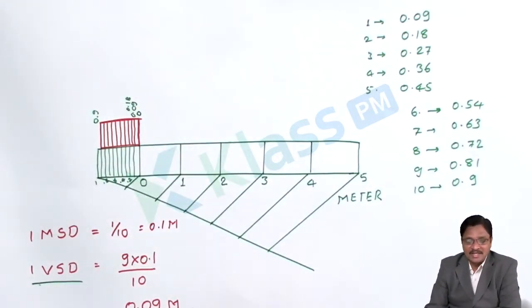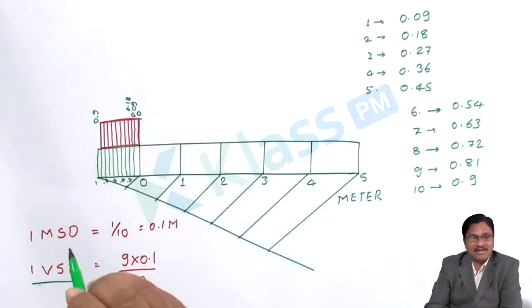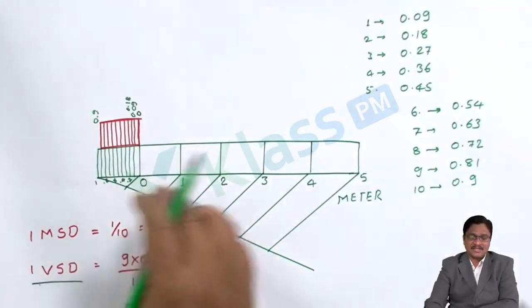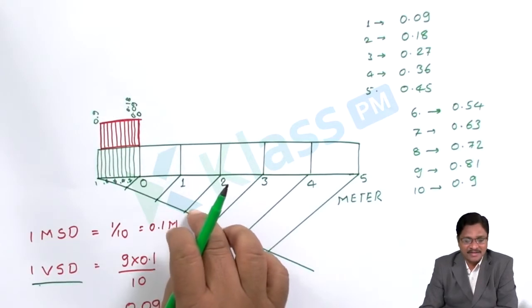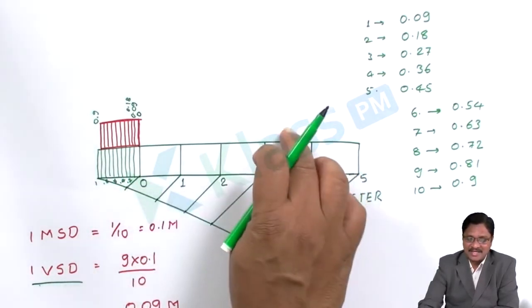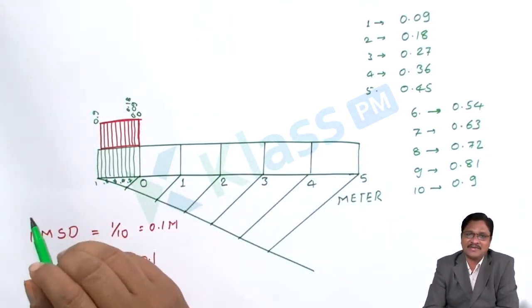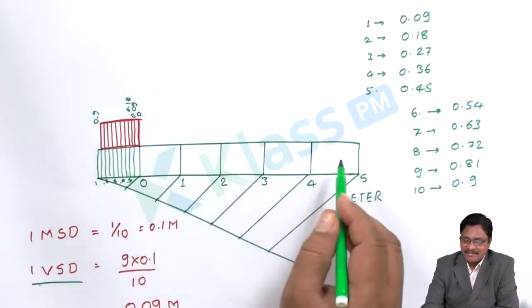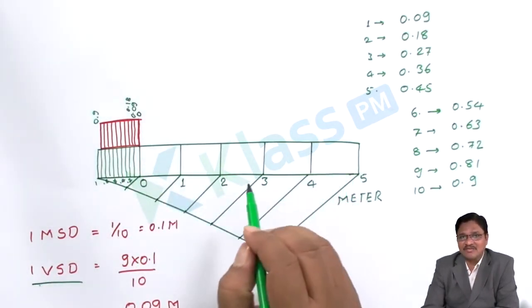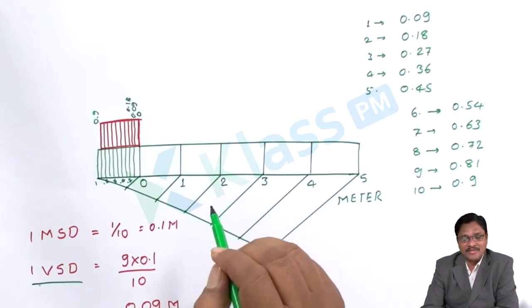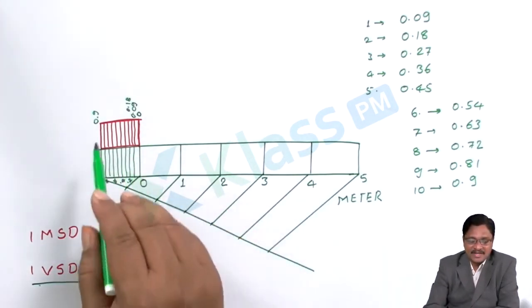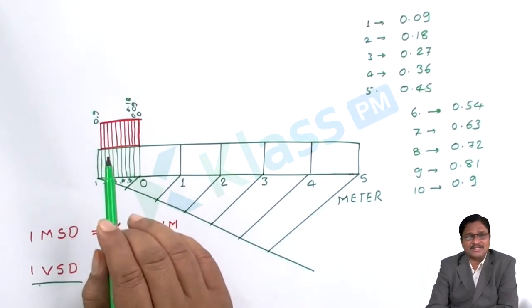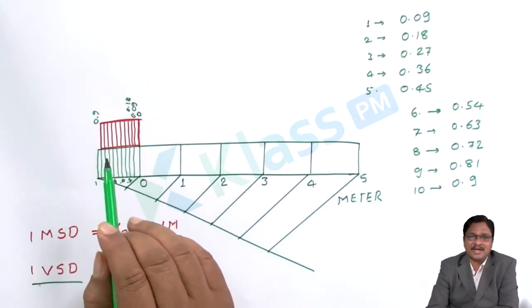So now to mention the required length. What the question is asking for is the construction. Regarding the construction of a forward Vernier, this is the method. First we have to draw the plain scale after calculating RF and LS. After that you divide it as the same plain scale we discussed in the earlier problems. After that, the extra thing we have to add is the Vernier. Considering the Vernier, there are two possibilities: a forward Vernier or a backward Vernier.